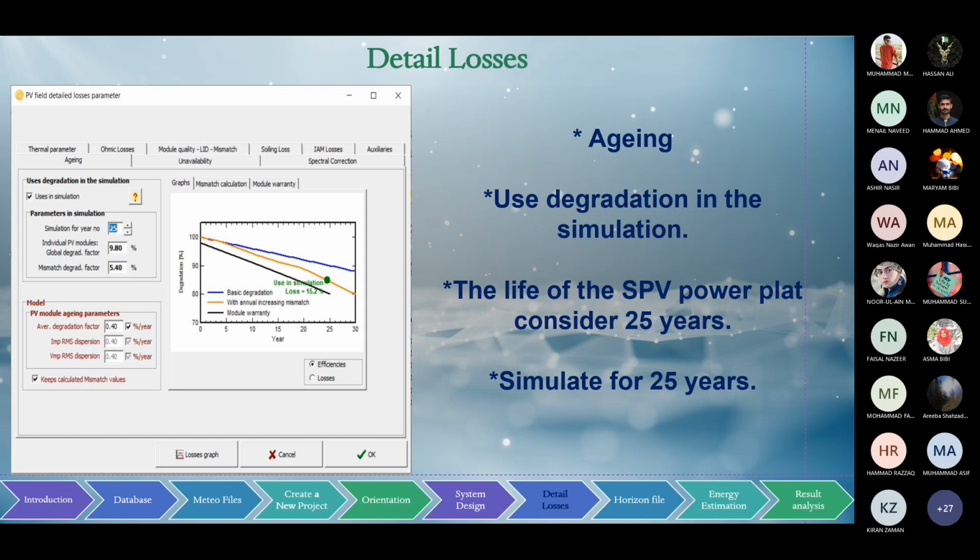So this is the aging factor. Now we are running a new solar PV plant, so the aging factor should be 1. Suppose you are running a 5 year or 10 year old plant, for example a 5 year old plant, and we want the PV system report. We have to enter the aging factor for 5 years, and for the annual degradation, from the second year onwards the annual degradation should be 0.4 percent. So 0.4 to 0.6 percent based on the solar PV module.